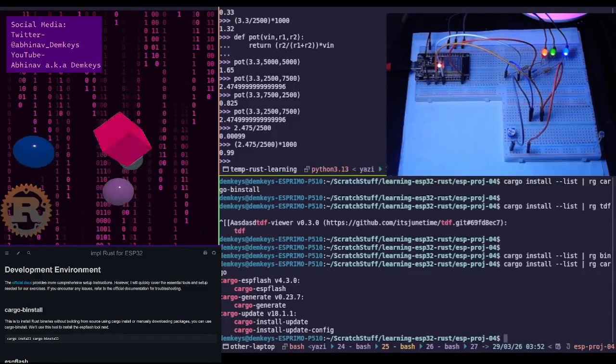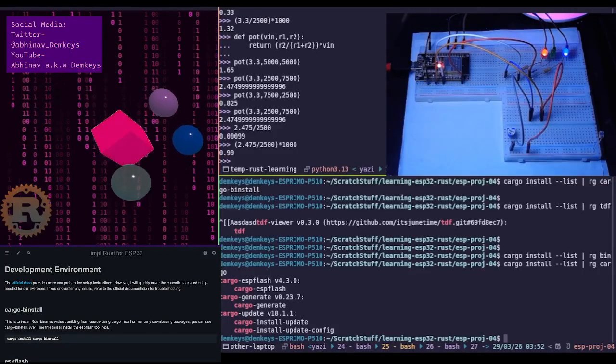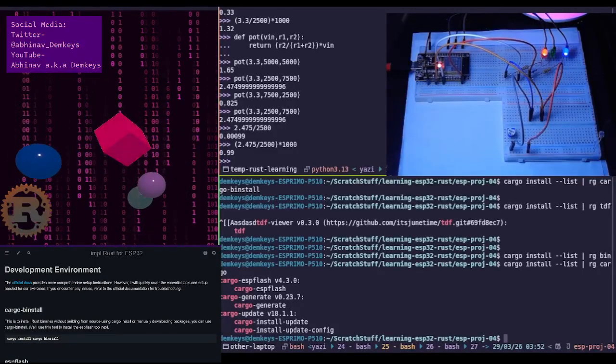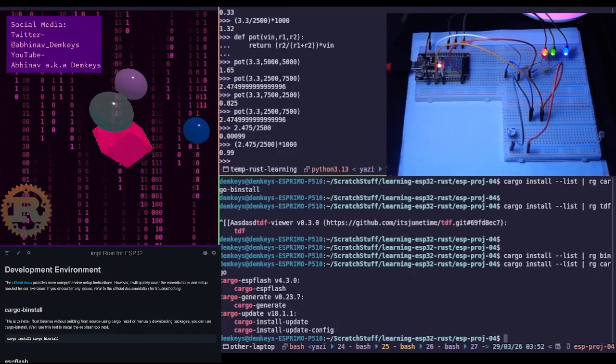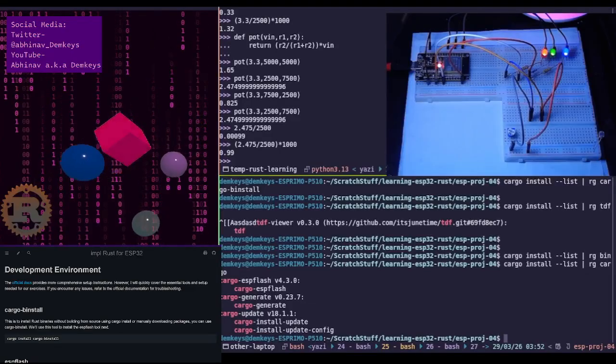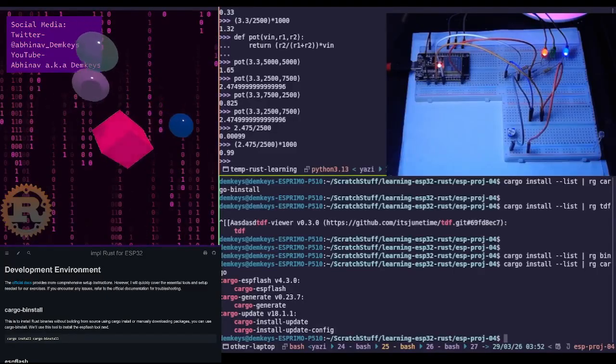Then there's flyback protection. Relays are electromagnetic. They use a coil of wire to create a magnetic field. When you turn off the power to a coil, the magnetic field collapses and generates a massive high voltage spike. You know what? Back EMF. This is the concept of back EMF.